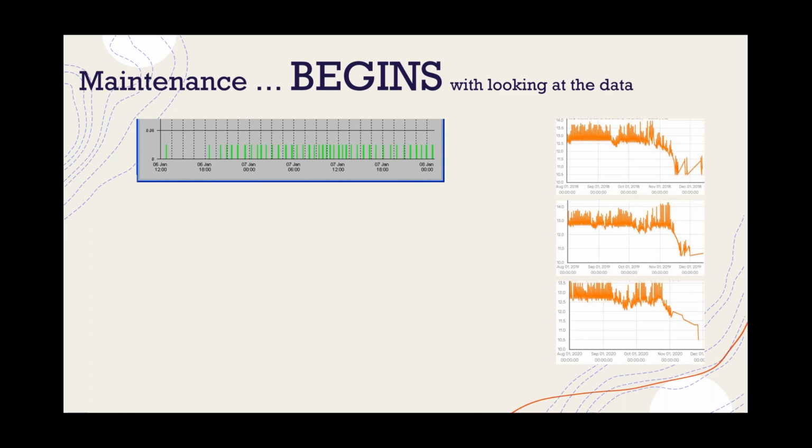Before you go out and look, this site, in the fall of the year, the battery keeps dying. Well, you go back and look for the last 3 years. Well, every fall the battery dies. It's not like somebody stole the solar panel. What's going on with that? Is the solar panel aimed in the wrong direction? There's a number of things that could create this problem, but knowing ahead of time before you get there allows you to go out there with at least a thought as to what you might find when you get there.